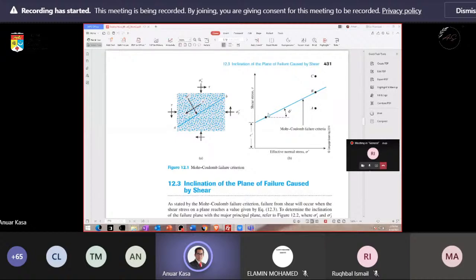In this case, we have like four points, but normally it's not like A, B, C here. Normally we run at least four times, so that we can plot this straight line, which intercepts the y-axis, or shear stress axis, at the value C, or cohesion, and the angle of that plotted line is the phi value for the soil.